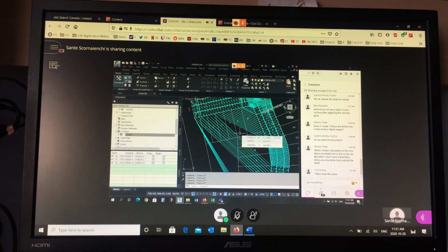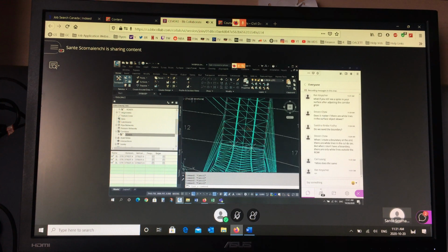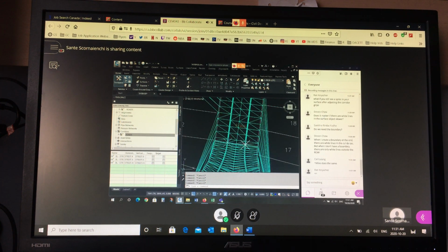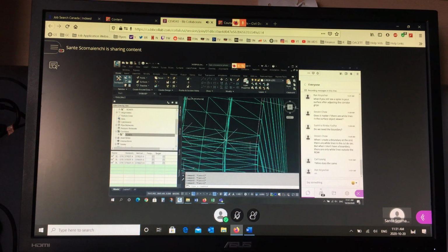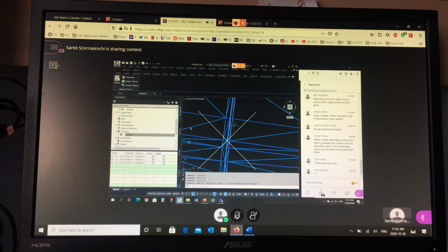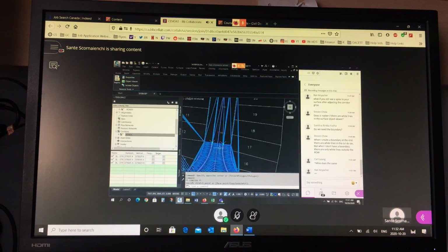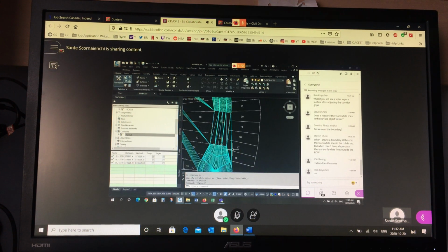Yeah, and again, it has to do with how tight you are, Stephen. It has to do with how tight you are with your grip edits. Okay, if there's any gaps or overlap, it's going to cause you trouble. Let me see if I can create one. Right, if you create an overlap here, like if this grip goes further, if you pull some of that 20-meter right-of-way in, it starts to get a little confused. So you have to be very, very specific.